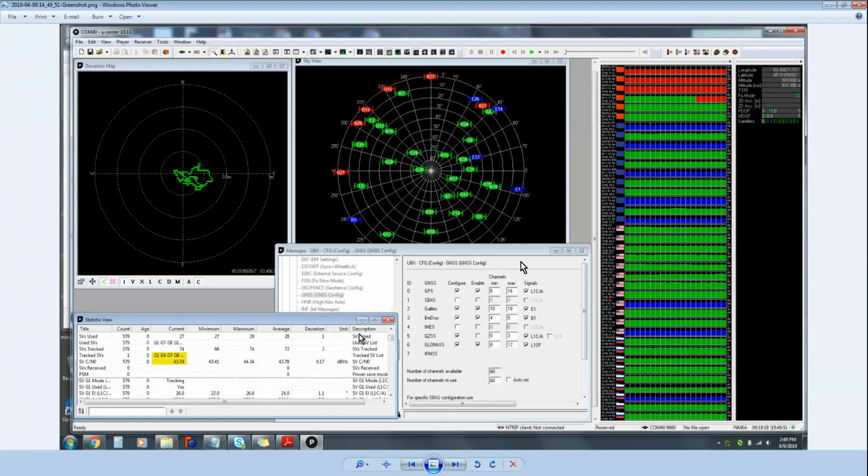So I don't know. And down here it says my NTRIP client is not connected, and that's because on the company network they won't let me out with that IP address. So I have to get my home computer, or one of those little Verizon hotspots like the one that Al has. If I plug that in, I can get out on cell phone data to get the correction data. By doing that, you just click a button and it says, okay, you've got correction data. All of a sudden, bam, it just drops down to 1 to 2 centimeters over here and works just great.